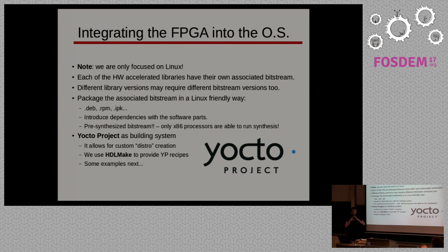By using HDL-make, we can generate recipes in which we specify to the Yocto project, the building system, how it needs to handle the HDL code in order to generate the package including the bit stream.